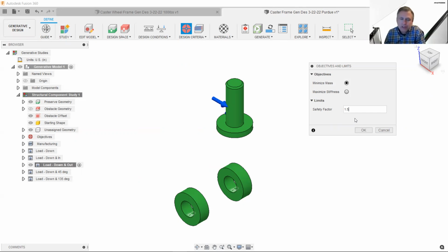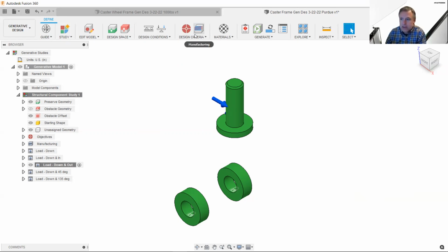Now, also, let me dive a little bit deeper. So with generative design, what we're saying now is a safety factor of 1.5 or higher is okay. Safety factor of 1.49 or lower is failure. That makes sense to everybody? Right. So again, that's our minimum safety factor. Doesn't mean that it won't be higher, but success is not lower.